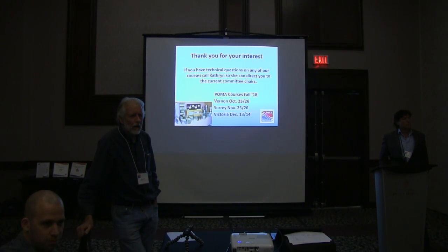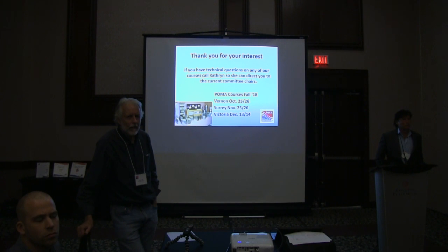ECM running constantly, constant fan system in the house, versus PSC. But with an air conditioning system, the PSC motor and ECM motor are each running near their load or their sweet spot, and not in the main operating range, so you would argue that there's no saving in cost. I'm looking for those cases where I see these systems installed with high static pressure, and sometimes the house is shaking because the motor is ramping up. What would be the electrical cost to run that motor at those static pressures?